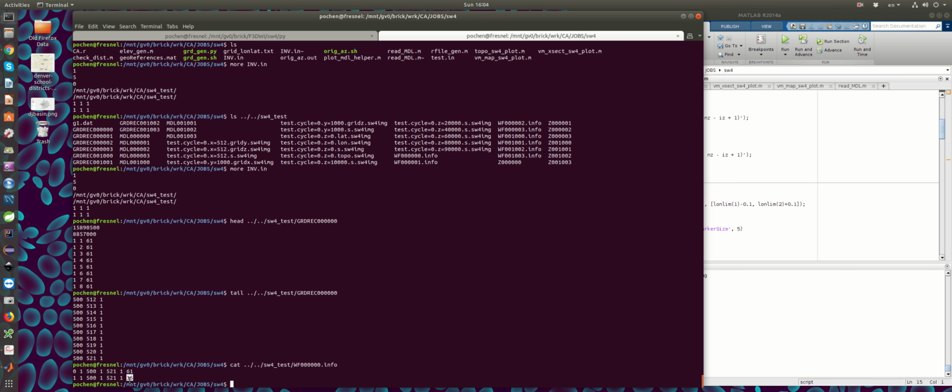Not exactly 35, actually it's going to go from 34 to 1, because one of those coordinates is duplicated. The topmost z coordinate for grid 0 is identical to the bottommost z coordinate of grid 1, so I have to skip one z coordinate at the interface, right?